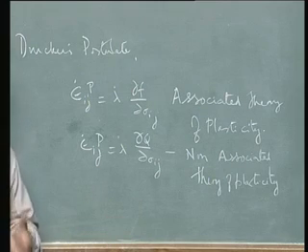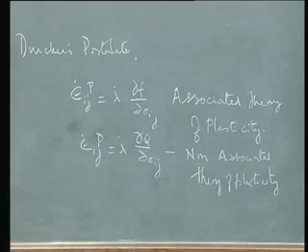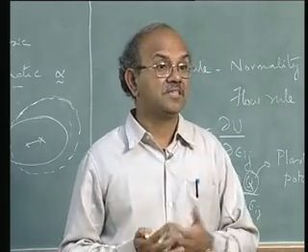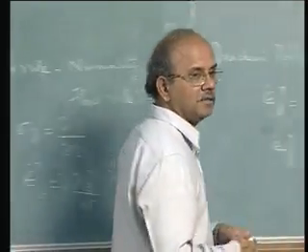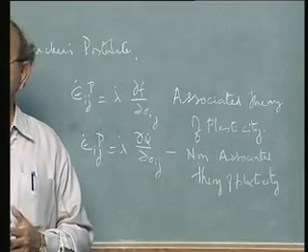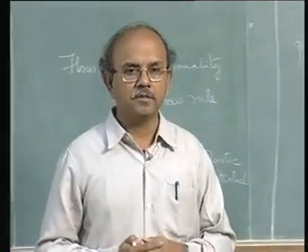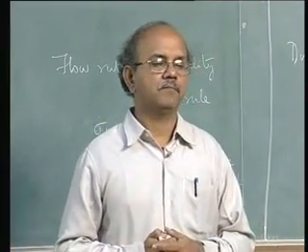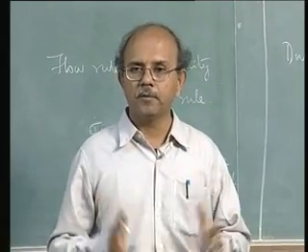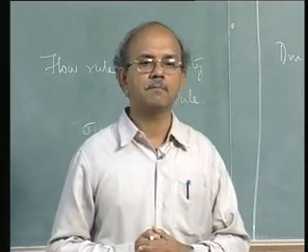Of course, there are now new theories to express even the behavior of metals in terms of non-associated theory of plasticity, very latest things that have happened, in order to predict some of the failures that take place in sheet metal forming, which is a very difficult area to look at. Probably all of you know the forming limit diagram and so on, and probably would have looked at how experiments are done to determine what are called forming limit diagrams.